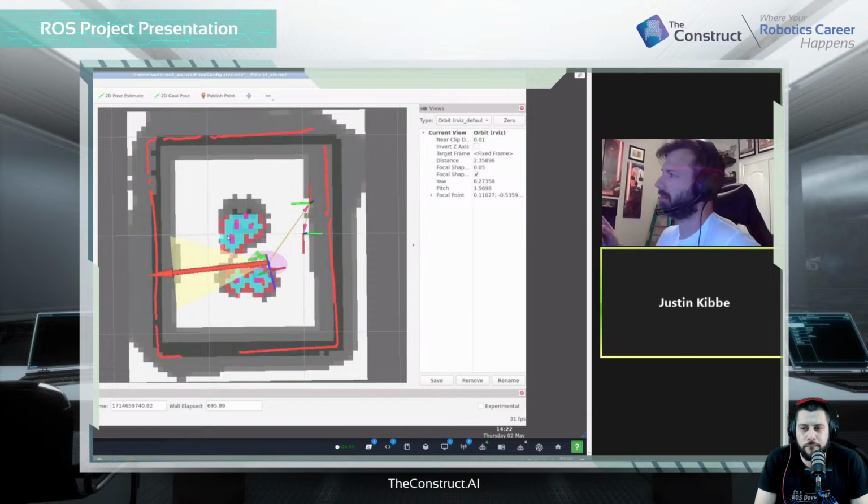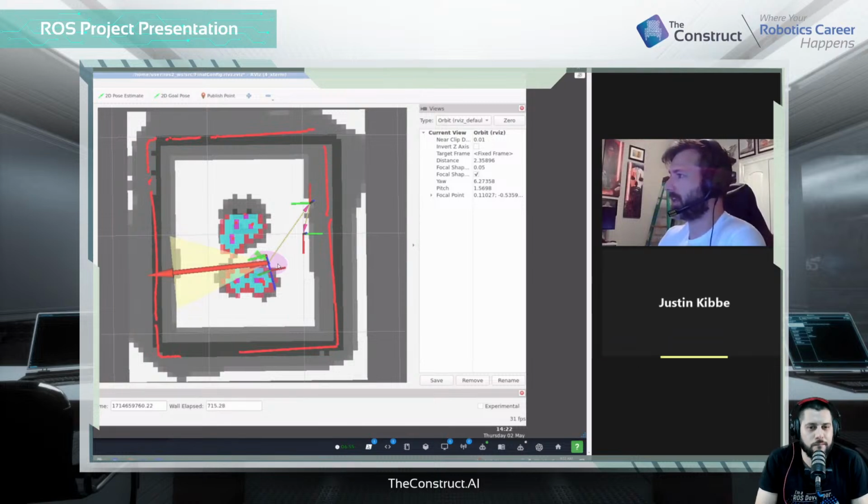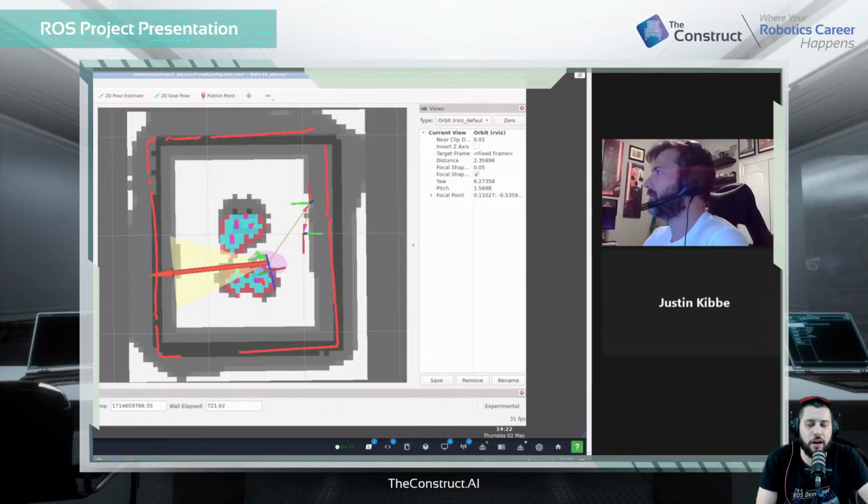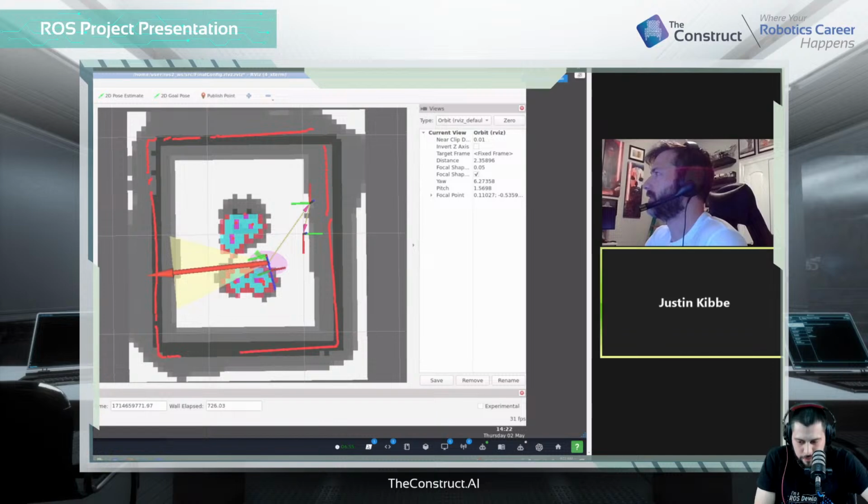Then I would run it around, and every now and then I would hit one of the movable obstacles from somebody's previous project or whatever that had been moved out of place. So I had to go back in and add the obstacle layer, add the local cost map and all that stuff. So what you see showing up now in these colors is so that I could actually avoid those during the moves. Right, the ones that aren't present in the map you created, basically. Right.